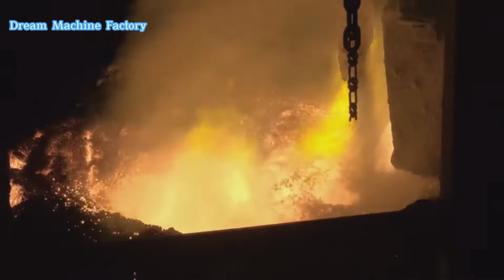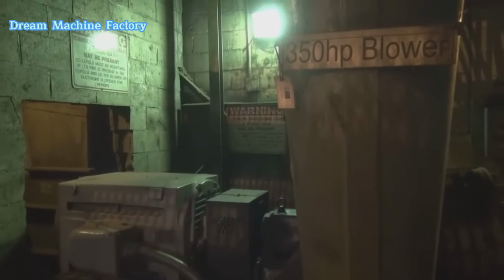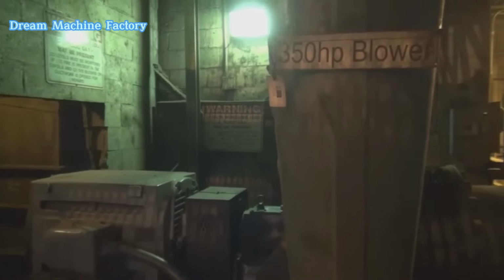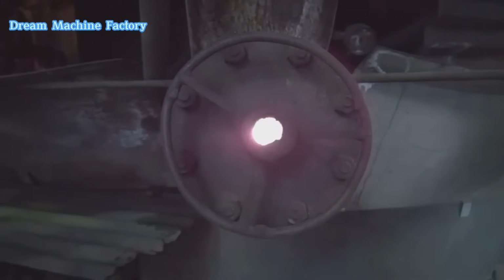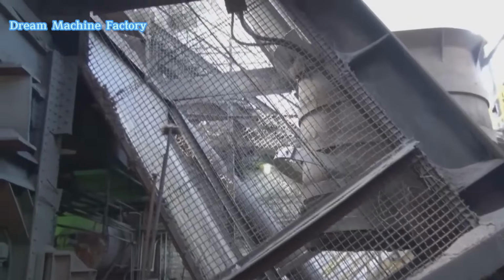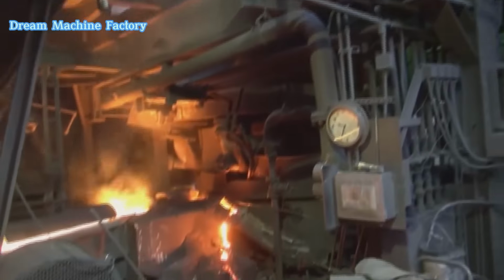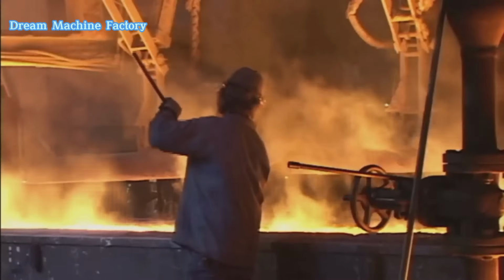The melting occurs in a cupola furnace, a tall cylindrical structure that operates continuously. The cupola is charged with alternating layers of scrap metal, coke, and limestone. Coke, a byproduct of coal, serves as the primary fuel source, generating the extreme heat required to melt the metal.